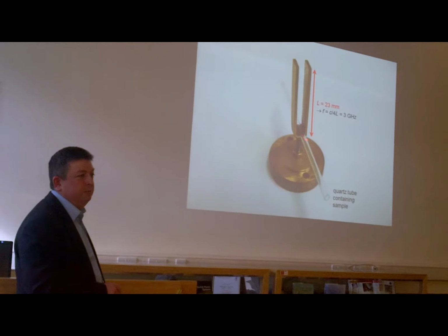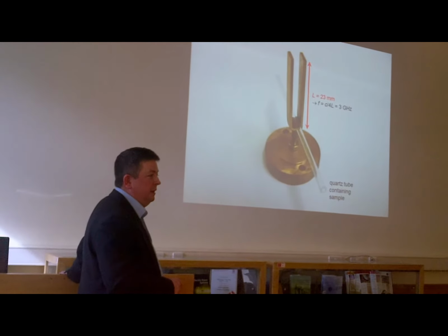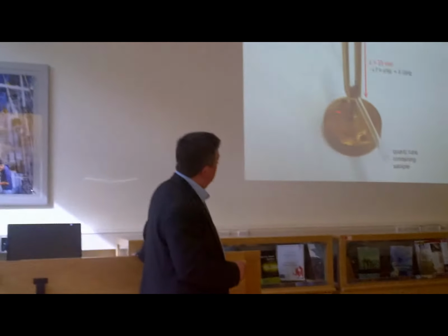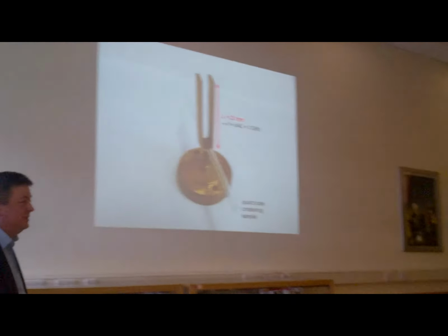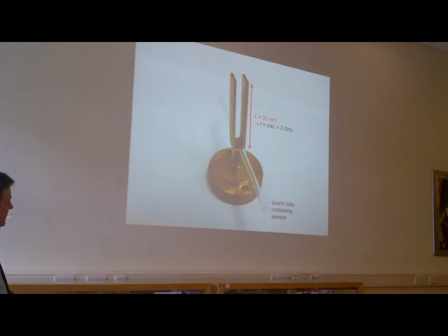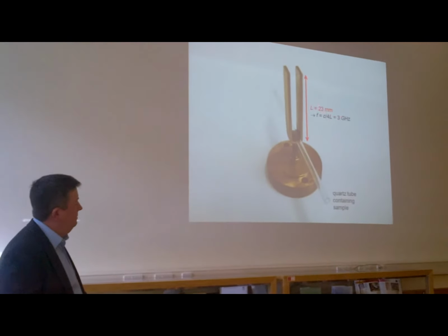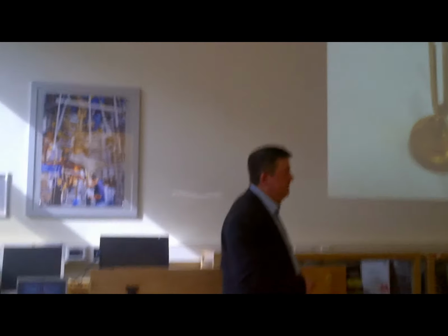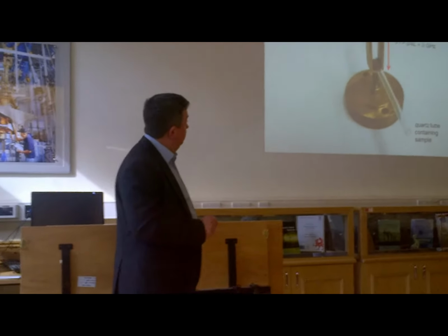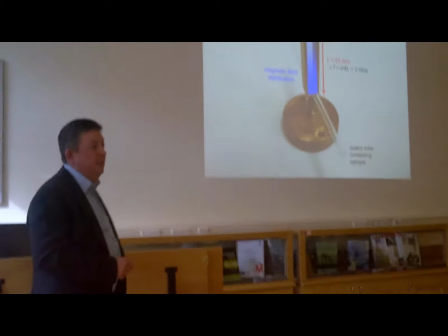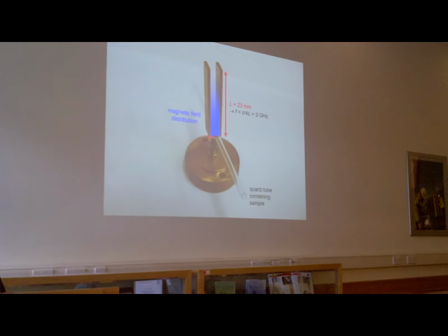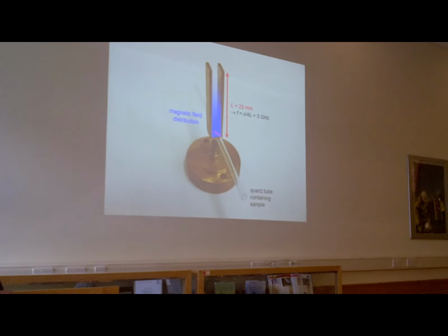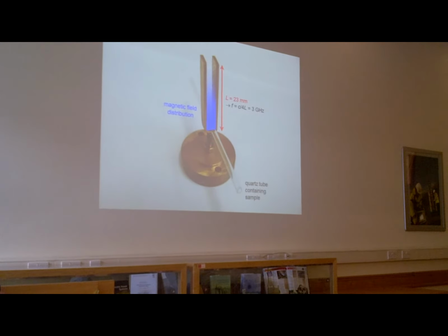This is a hairpin resonator. In simple terms, it's just a bent U-shaped piece of copper. But of course, that's a parallel plate transmission line with a short circuit down that end and an open circuit up at that end. So that sets up a standing wave along it. And the fundamental resonance is a bit like an organ pipe calculation where you set the length equal to a quarter wavelength, and you choose a length of 23 millimeters, and lo and behold, it goes at 3 gigahertz. It's as simple as that.